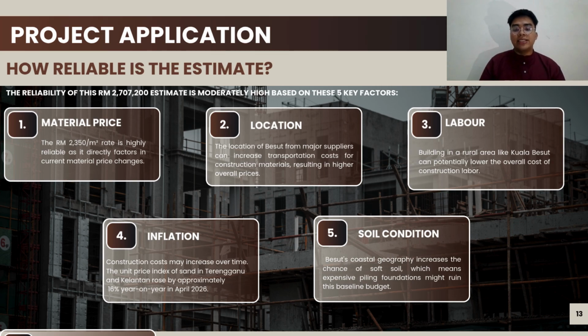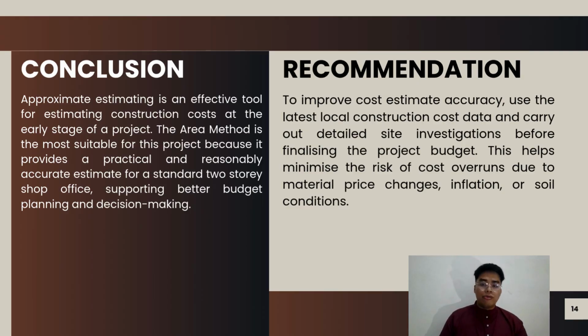Four, inflation. Costs can change over time. For example, the price index of sand in Terengganu rose by roughly 16% year on year in April 2026. And last but not least, soil condition. Besut's coastal location means there is a high chance of soft soil, which could require an expensive piling foundation that could affect the baseline budget.